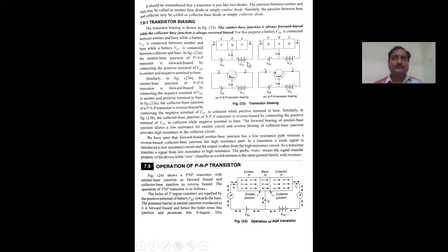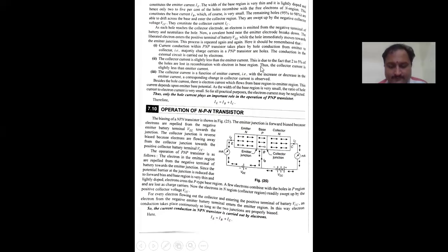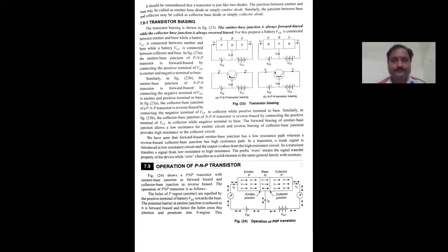At 0.1, the current must be 0. At 0.2, current must be 0. At 0.3, current must be 0. After 0.3, the value is 0.001. Then it can be concluded that it is germanium. Otherwise, after 0.7, it is silicon. Another case we can observe.